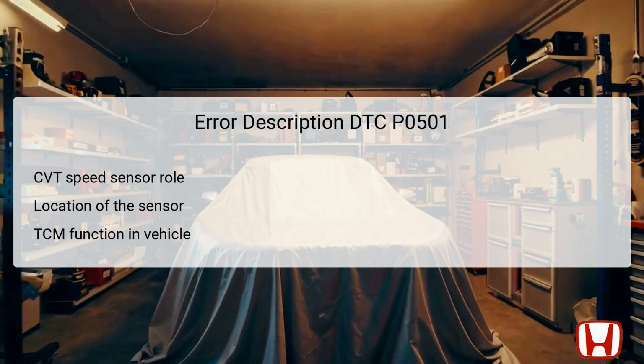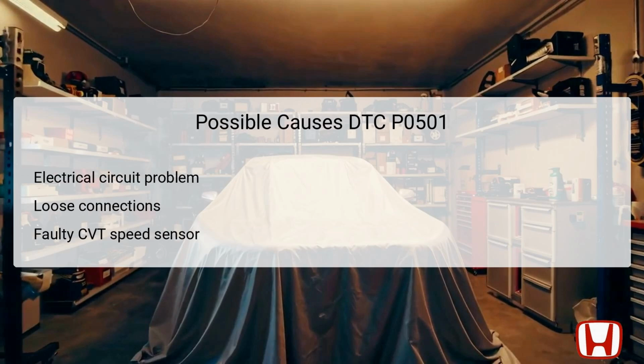As this is an electrical issue, pinpointing the sensor's location and ensuring its connections are secure is critical in diagnosing the P0501 DTC. Remember, when troubleshooting this specific code, you may find electrical connections or damaged wiring to be significant contributors. The primary cause of DTC P0501 is an electrical circuit problem within the system.